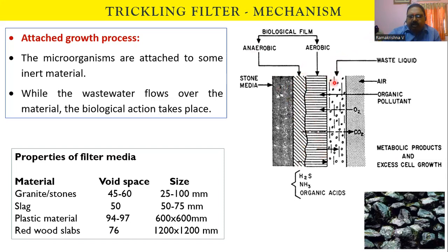So the microorganisms receive the air from the atmosphere and decompose the organic solids in the wastewater into carbon dioxide and other aerobic decomposition products. While the wastewater flows over the material, the biological action takes place.